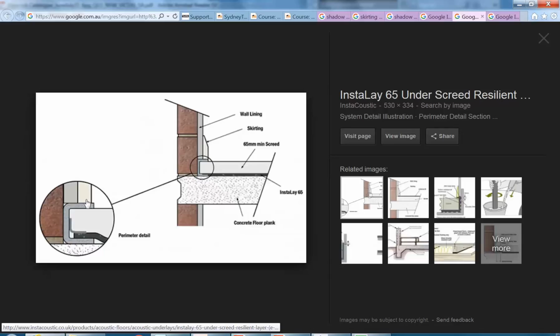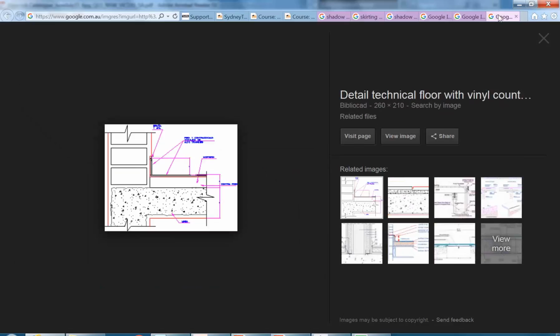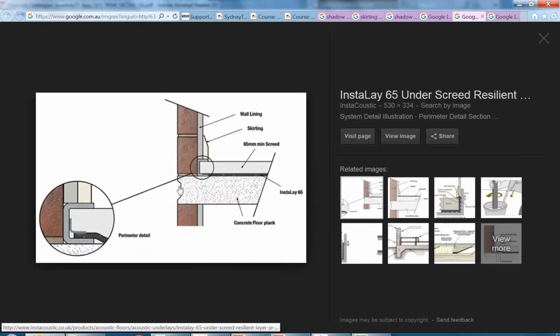Yeah, that's right, so they'll have just like a quad lining, or sometimes a plastic thing for different flooring systems. Yeah, so you should have a gap. It's really important actually to have that gap if you think there's any chance of the floor lining changing, which with residential you should always allow for. So yeah, that otherwise is a pretty standard detail.